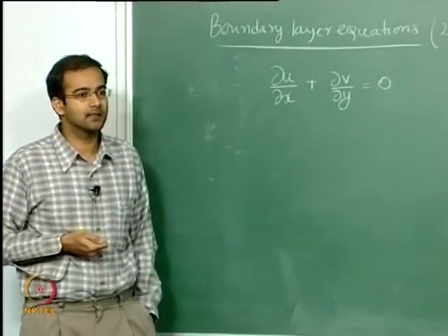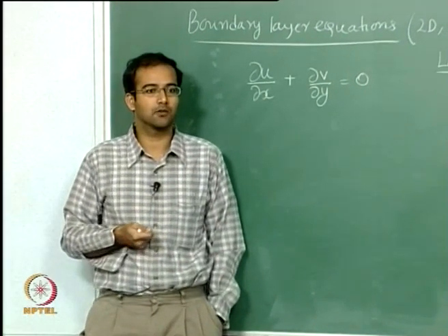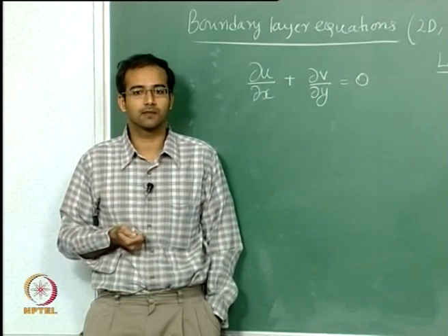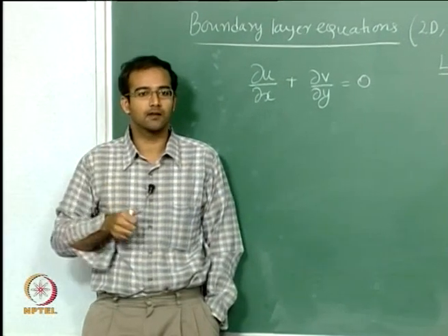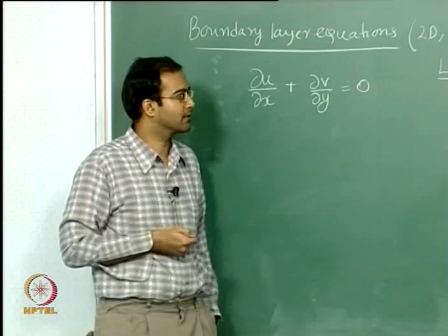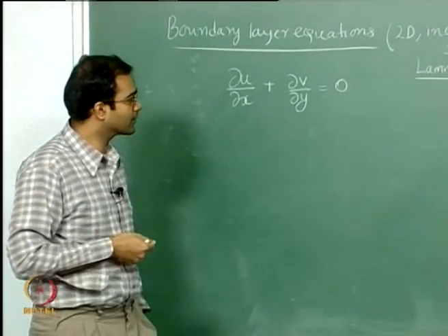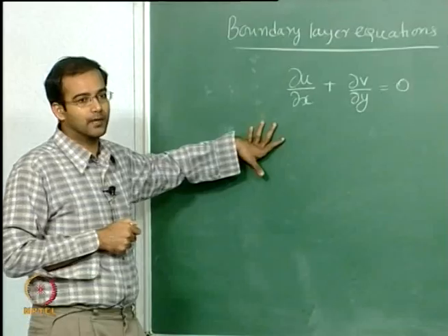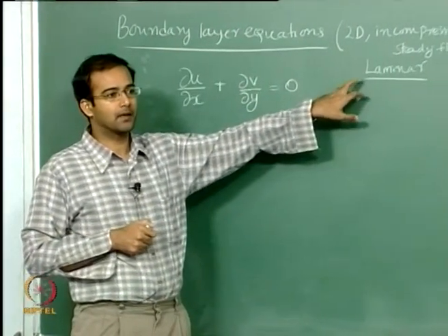As such, if you solve the Navier-Stokes equations as they are there is no problem, but most of the time you cannot resolve all the scales, and therefore you have to approximately model what are called averaged quantities, and that's where the RANS equations come. So far we have not discussed those things. I am just looking at plain Navier-Stokes equations and approximations. So you can say safely that this is mostly applied to laminar solutions.